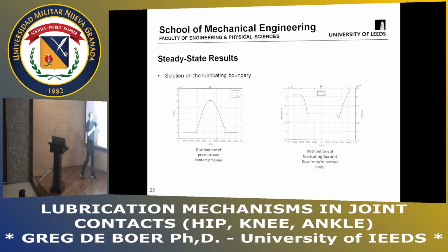The other thing to look at is this graph on the right, which is quite an informative graph when you're a tribologist. The key thing is if we look at this parameter Q, this is the flow rate of the lubricating flow, okay? And remember this part here is where these parts are non-zero, so that means it's in contact there, or the films are very small, and you can see that the flow rate comes down to almost zero.